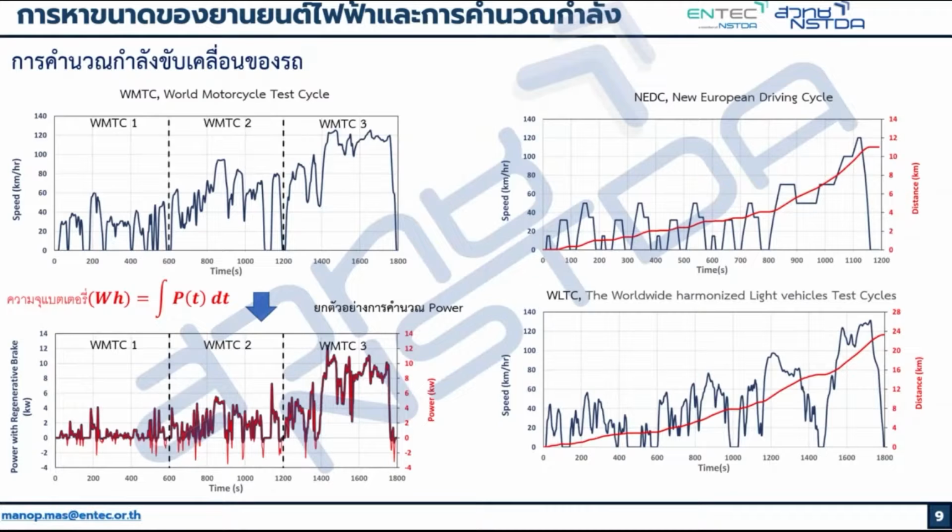So this graph is about the driving cycle. The speed depends on the time. The below is to calculate the power depending on the model, as a sample of power calculation. The power peak occurs not at high speed but when accelerating, for example from 0 to 80 km/h.